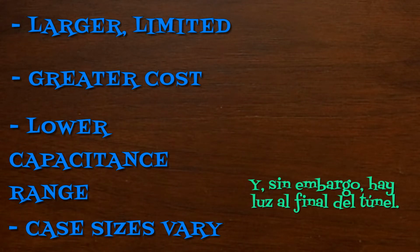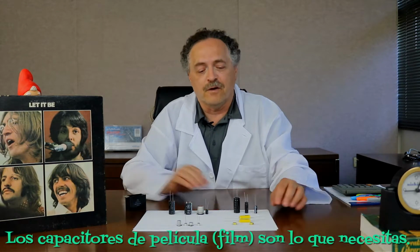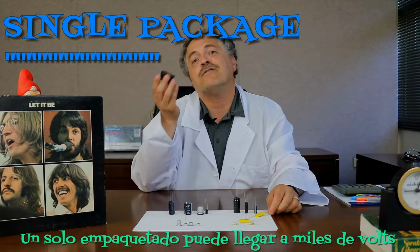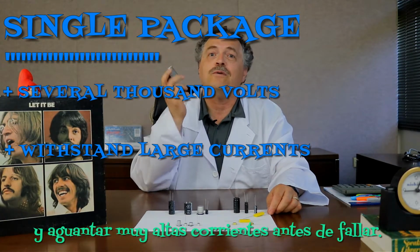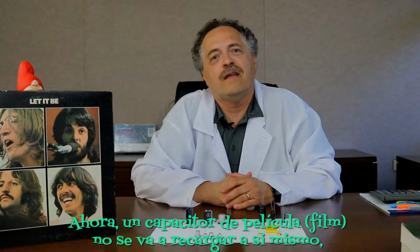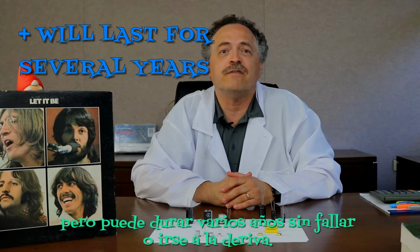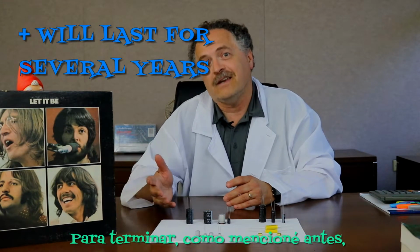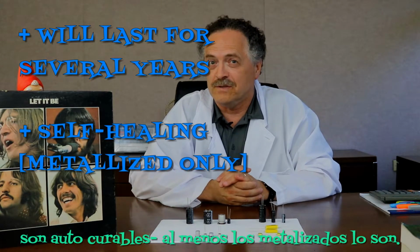And yet, there's a light at the end of the tunnel. You need a cap for AC and DC application? Film caps are your guys. A single package can reach several thousand volts and can withstand very large currents without calling it quits. Now, a film capacitor won't recharge on its own, but it will last for several years without failing or drifting. Lastly, as I mentioned before, they're self-healing. At least the metallized ones are.